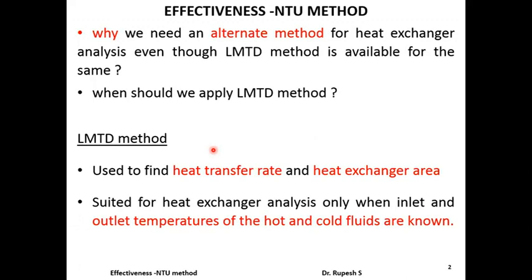First of all, we will see when we apply the LMTD method and what are the data requirements for applying the LMTD method. The LMTD method is a convenient method for heat exchanger analysis when the outlet temperatures of hot and cold fluids are known and our objective is to find the heat transfer rate and heat exchanger area.